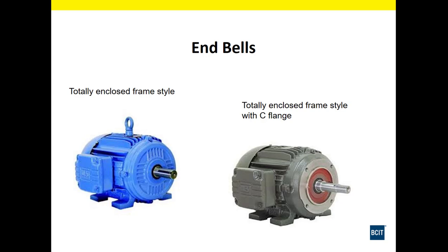The end bells also can have slightly different designs for some of these TEFCs. We have on the left a totally enclosed fan-cooled style frame, and then on the right we have the same totally enclosed fan-cooled style frame, but it has a C flange, we call it, mount on it. That's for mounting.